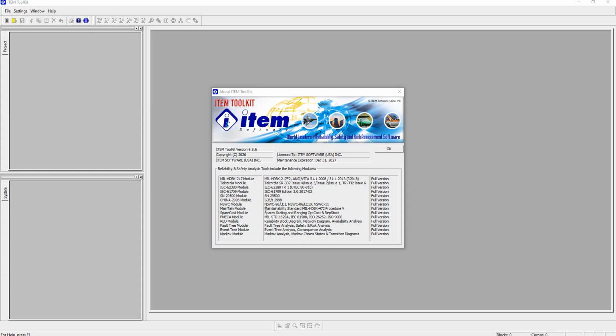Typically, a reliability engineer looking to perform a reliability analysis on their system would first import their bill of material into one of the prediction modules to obtain all the failure rates. Once this is done, they would like to take their prediction system across to a FMECA system to perform functional safety analysis. Here in part 2, I will show you how we would use an existing prediction module with blocks and components and convert this to a FMECA module to perform our functional safety analysis.